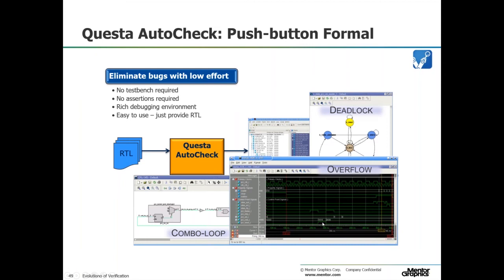If you have timing issues in your design, it might find certain things, and it will generate a timing diagram that says this is an issue that you are likely to have. So as I said, it's a one-stop push button formal check of your design. There's probably 60 or 70 different checks that all RTL code should obey these rules.